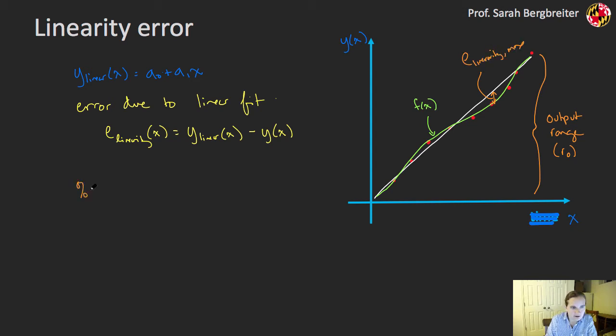And then I'll have a percent E, and I'm just going to shorten it to L here. Max is equal to that maximum linearity error, in whatever the output units are, normalized by the output range, and then of course times 100 to put it in percent. So this is given effectively as percent full scale output range, something that you might often see in a data sheet.